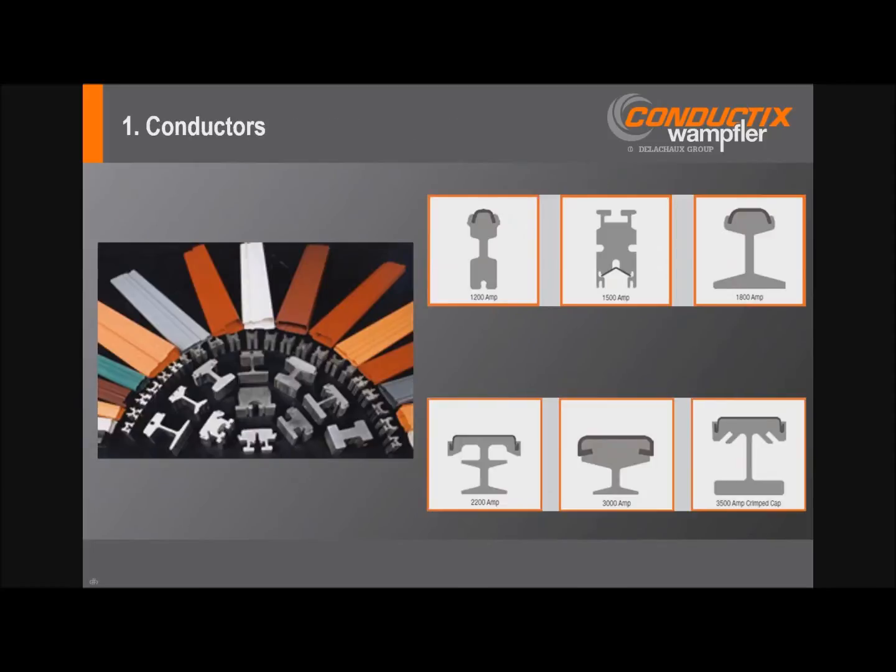So for the conductor rail, the most prevalent and cost-effective configuration for modern power rails is extruded aluminum conductors with a stainless steel contact surface. The aluminum provides a sufficiently low resistance, about 55% the conductivity of copper by volume, with excellent strength and stiffness, lightweight, and good corrosion resistance. The stainless steel contact surface protects the aluminum from mechanical wear of the collector shoe and provides improved resistance to electrical arcing. Now, this combination of materials really provides a durable, cost-effective, and electrically efficient conductor of sufficient mechanical strength and stiffness.